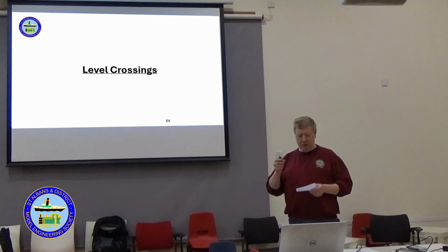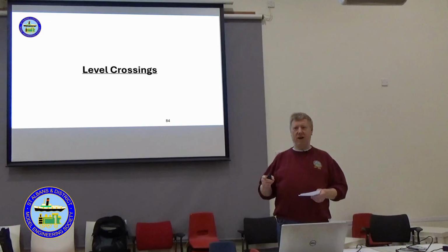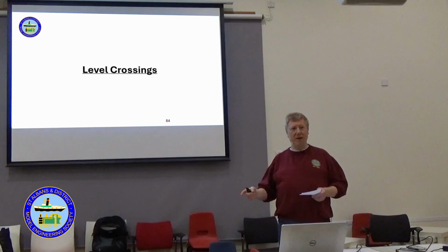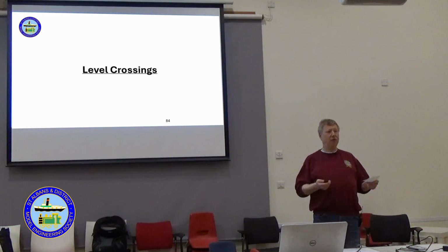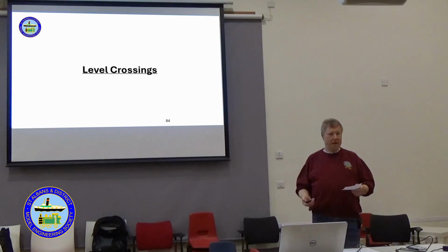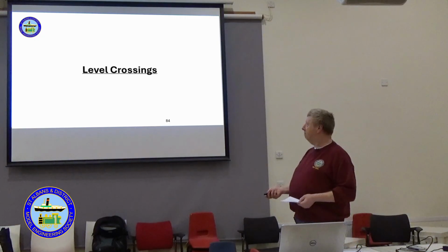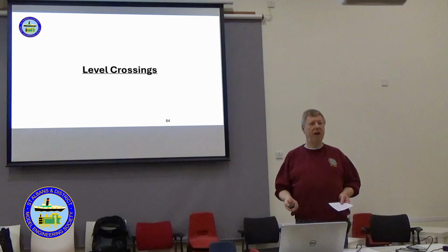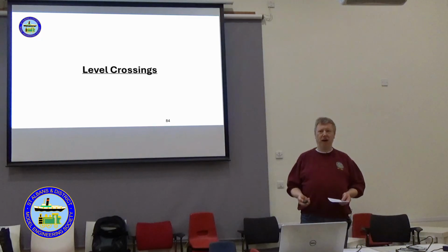Within the time it takes you to see that hazard, you've got enough time to realise there's a hazard, slow down and stop before you hit it. Another way of saying that is your sight distance is longer than your stopping distance. Make sense? Now you may think that's pretty obvious, but it's a critical thing for man-operated machines. And it's not true for trains.